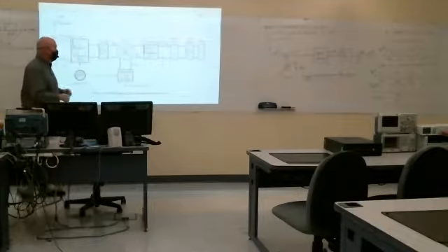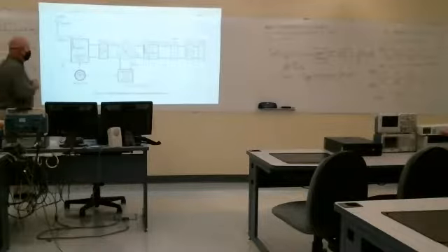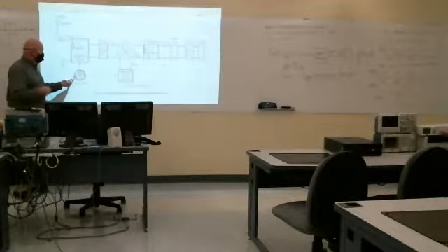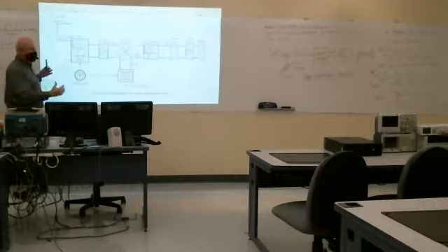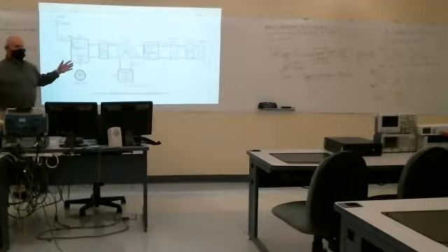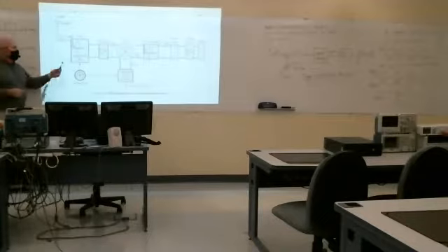So this is almost as good a picture as I drew. Here it actually shows the tuning knob adjusting the center frequency on a bandpass filter here at the front end. That's not where the channel selection is done. It's part of AM radio because the AM radio band is so wide, it has to eliminate what's known as an image frequency.